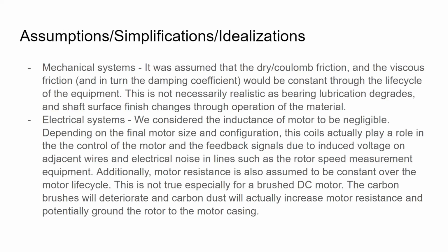Now, there were a few assumptions and simplifications that we had to make, specifically in the mechanical systems. We assumed that the frictions associated with the mechanical systems stayed consistent throughout the entire life cycle of the component. That's not necessarily realistic, as bearing lubrication degrades and shaft surface finish changes throughout the life of the material.